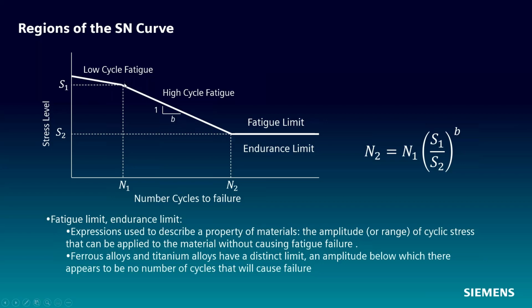For FDS, we're really only interested in this high cycle fatigue region of the curve where elastic deformation is appearing. And this is plotted at the maximum stress level that occurs before material failure. And what we're interested in particular is being able to understand the slope of this curve.